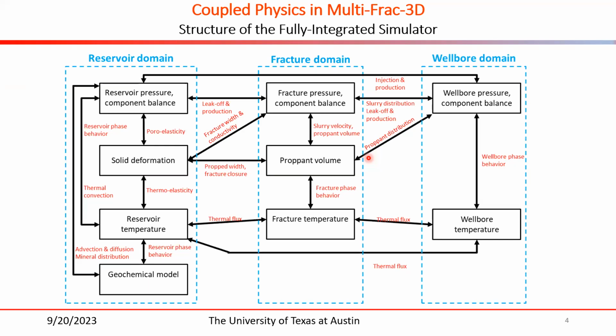I'm not going to go through any of the details of the model. It's all been published and it's available. If somebody's interested, I'm more than happy to send you more details. One of the unique things about the model is that the fractures that we create are modeled explicitly. We are not really modeling fractures as high permeability grid blocks. We're actually modeling these fractures very explicitly, where you can calculate the displacement and the width of the fracture and the stress that arises as a result of the creation of this fracture. So interactions between the fractures and natural fractures can be properly accounted for.